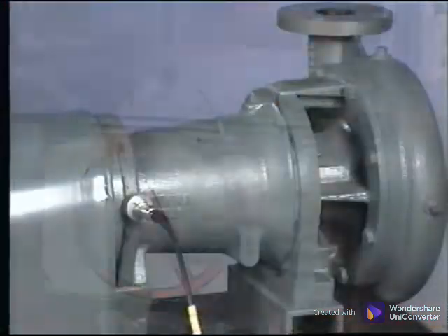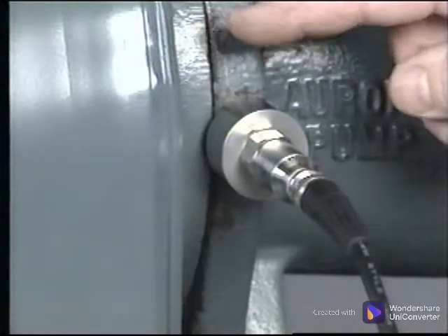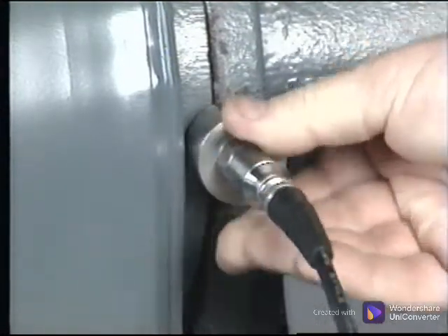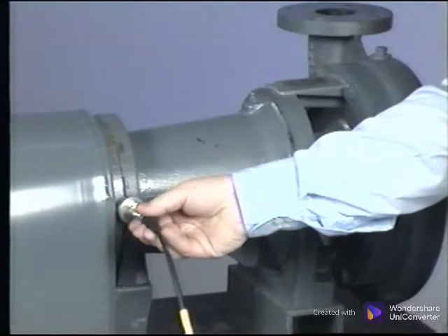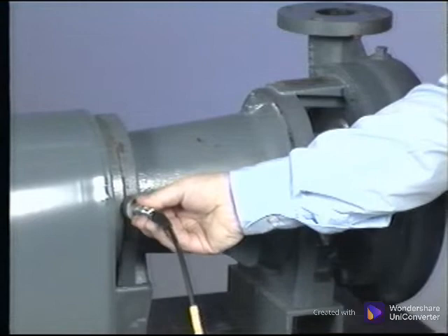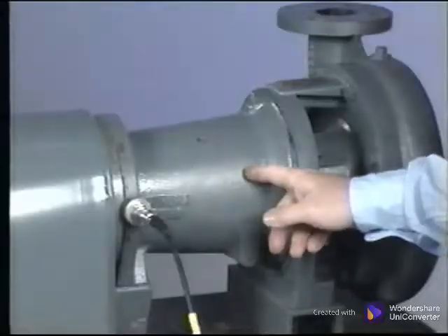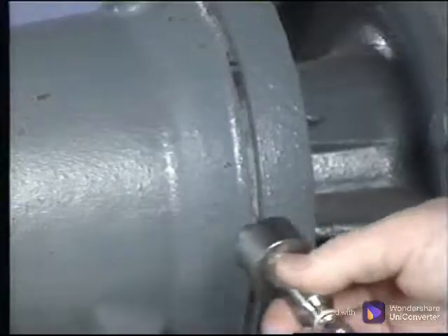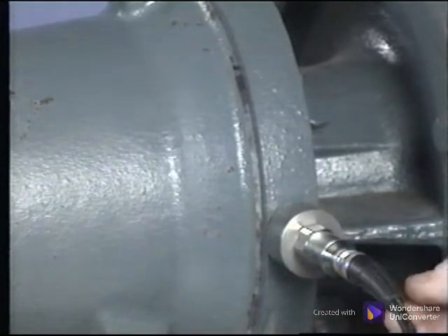On the pump, the horizontal measurements should be made on this flange because the bearing is mounted directly in line here. Be sure the sensor does not cross the joint, which may cause it to rock and generate erroneous frequencies. The center section of these pumps is hollow, and measurements should not be made here, as the signals will not be accurate. The outboard bearing is located in this area, and the horizontal readings should be made here.